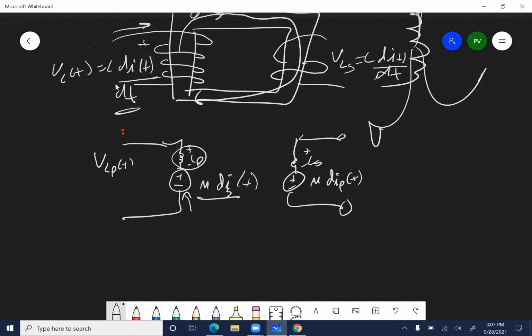You're moving power through the transformer because as you increase the amount of load, the IS of T, you're actually going to increase the amount of power that is conveyed. So how do you make a transformer work harder? You just put more load on it, meaning you allow more current to be pulled out of the transformer. That's all you're doing, you're working it harder.